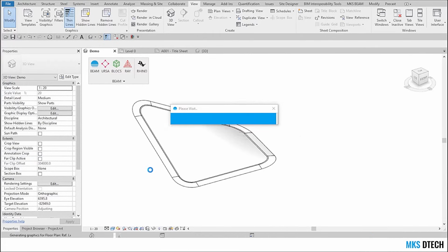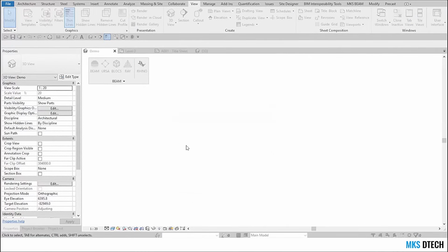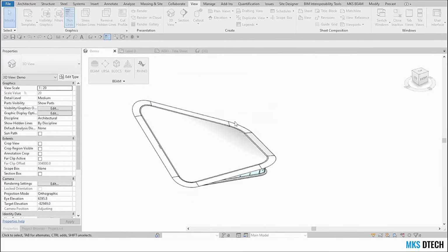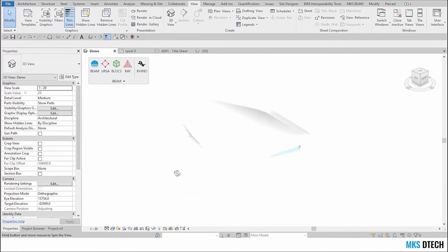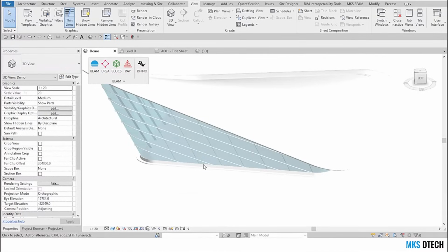If you close the view and you work on a drafting view, for example, you can get much faster speed for imports in different scenarios. But it's also good to see what's going on. I can also close these and stop my import at any time. Okay, now Revit is loading the family, and sometimes it hangs, but depending on your machine, it's more or less fast. So you can see now I have my objects.